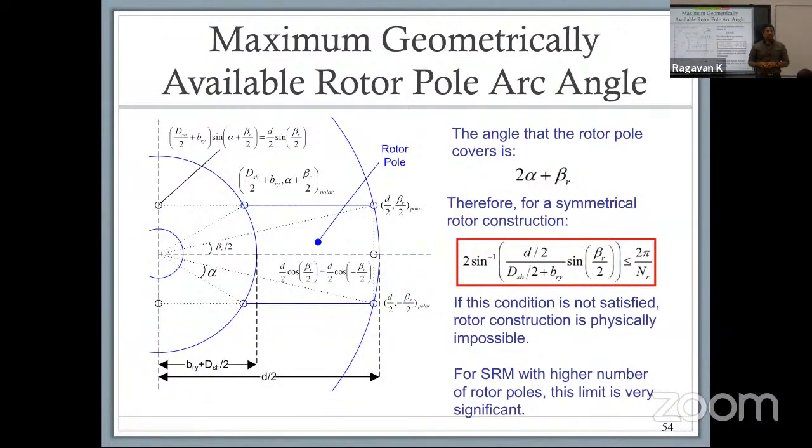In particular, just think about the idea of the slot. We talked about permanent magnets and the slot that comes with it, the notch that you have in the rotor structure. That gives you a substantial improvement in your torque ripple. There's a reason why they were doing that, but you need to know where to place the slot with designer experience, or you have to have an automated process that does a sweep and specifically identifies what that optimal slot geometry should be and where it should be placed, right?